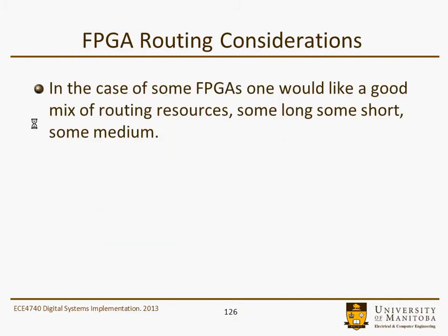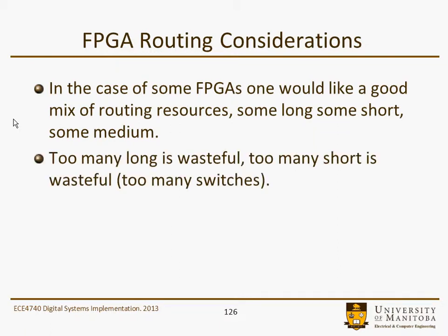Now we want to talk a little bit about FPGA routing considerations. In the case of some FPGAs, one would like a good mix of routing resources, some long, some short, some medium. You can justify that because you're probably going to need a mix of routing resources when you route any arbitrary kind of design. And the idea behind the FPGA is the ability to route an arbitrary design.